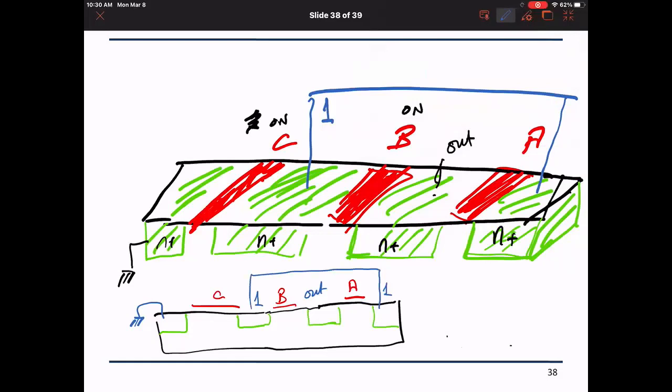So how many diffusions are there for node 1 now? 2, right? Yeah. Okay, so practically we draw it as this stretch with C, B and A, where the common diffusion between C and B is really the common one, and the one between B and A is for the out, and so on and so forth.